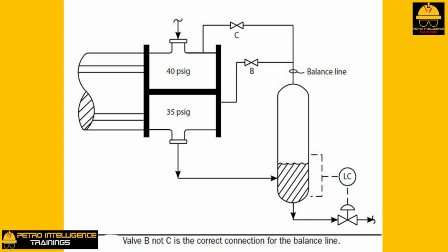The natural tendency is to maximize the drum pressure to promote condensate drainage from the drum by keeping valve C open and B closed. Then the pressure in the condensate drum would be 40 psig. But the pressure in the lower half of the channel head would only be 35 psig. You can assume a 5 psi delta P on the steam side. How can water at a pressure of 35 psig flow into a vessel at 40 psig? The only possibility is condensate backup equivalent to 5 psi.